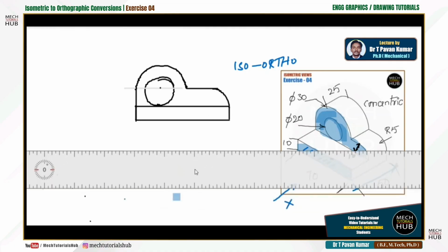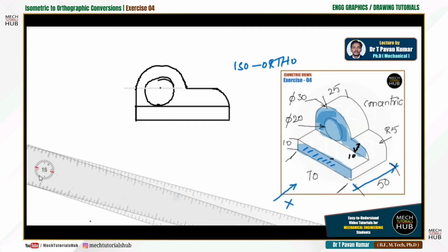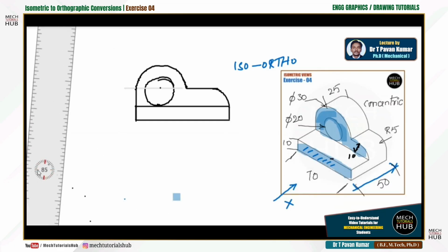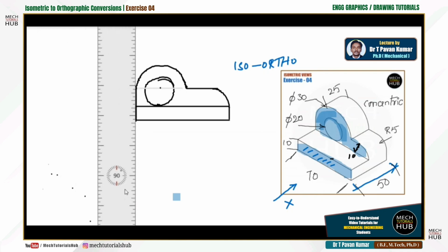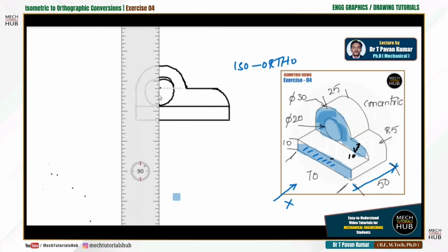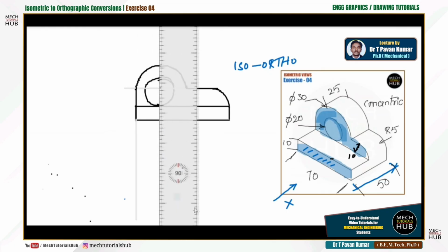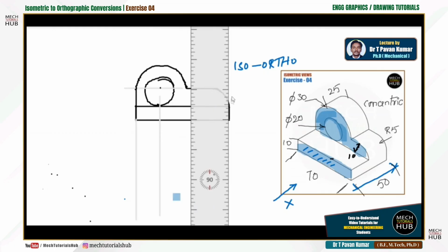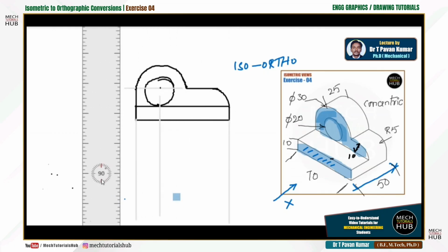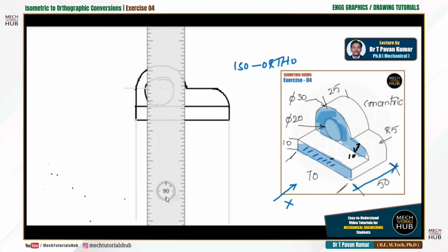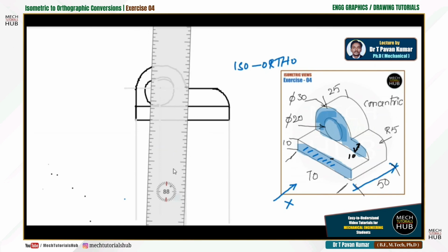Okay, front view. Followed by that, to get the top view, again rotate your drafter scale, make it vertical, or else you can use the other, perpendicular scale of the drafter, and wherever you get intersection points, lines or edges, drop a 2H line from the center, again one more 2H line. These 2H lines you can keep as they are for your further construction. Alright, 2-3 edges I have taken. Now this is one more edge here where the semicircle got dropped. Here drop one more. Now rotate back to 0.